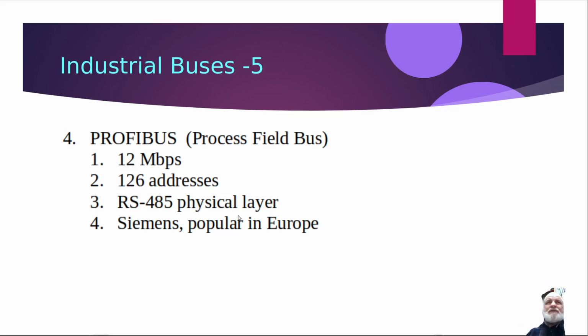There's also Profibus. Profibus, I believe, was created by Siemens in Europe. And again, it's built using the same physical layer as RS-485. It can handle about 126 devices, but it has a much higher speed of about 12 megabits per second.